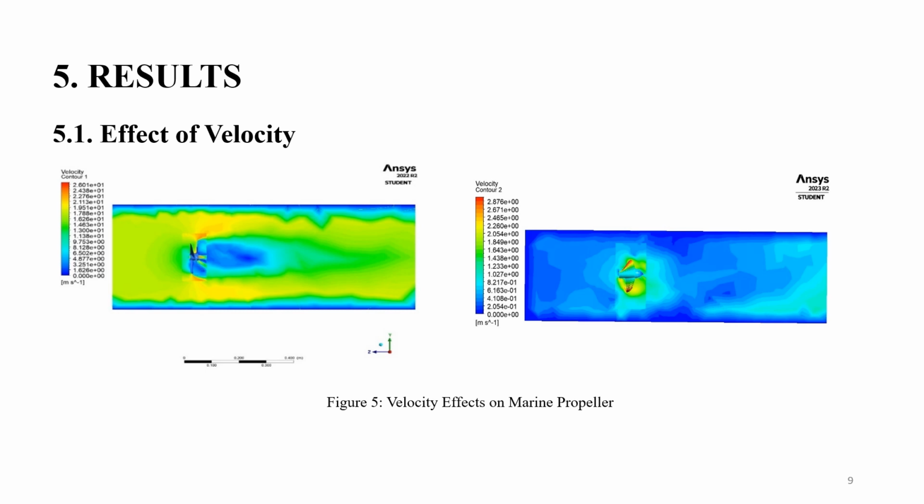In essence, the velocity contour analysis provides a clear depiction of how the propeller's rotation influences fluid dynamics. The pressure disparity across the blades generates a propulsive force, culminating in a pronounced fluid motion with elevated velocities. Understanding these velocity patterns is critical for assessing the propeller's performance and comprehending the intricate dynamics governing fluid flow around the rotating blades.